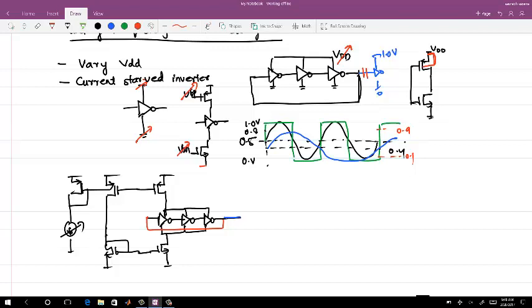So in place of a square wave, you will see a sinusoid. Let's say you take any ring oscillator. You can do this experiment. Take a ring oscillator designed at the highest frequency, and then change the supply to the point where it still triggers and the oscillator still works. You will see a complete change in the waveforms. You will see square, sinusoidal, triangular, and all the things. And that happens because of the changing strength and the bandwidth of these devices.